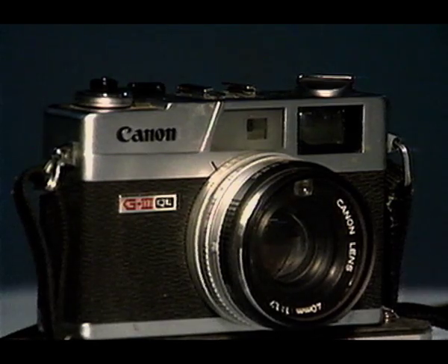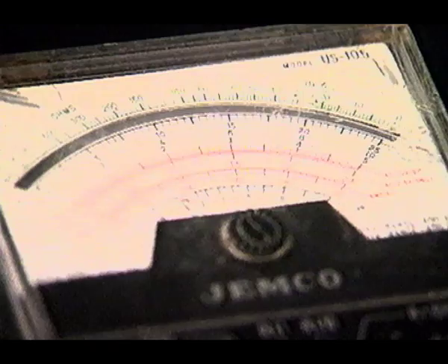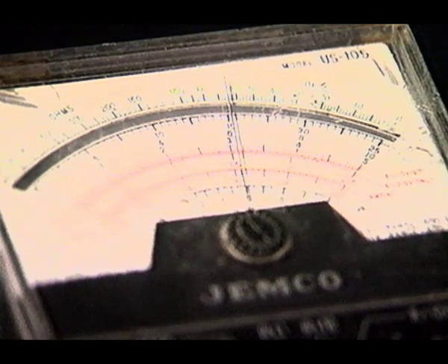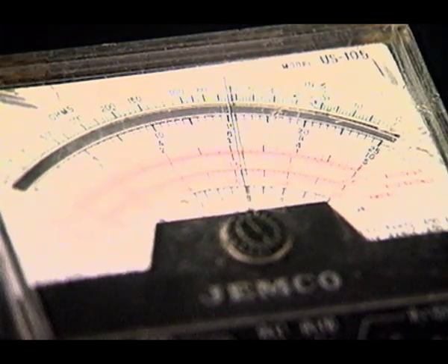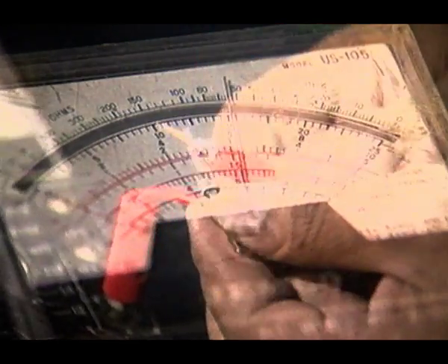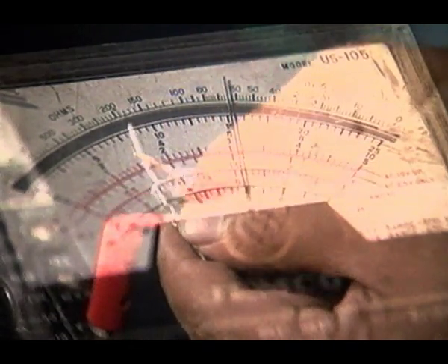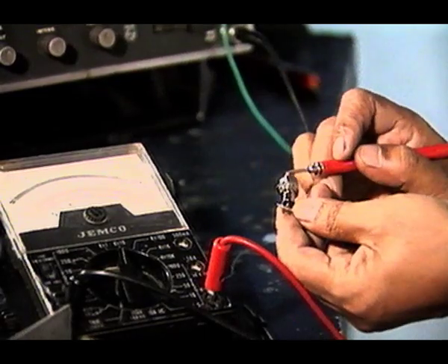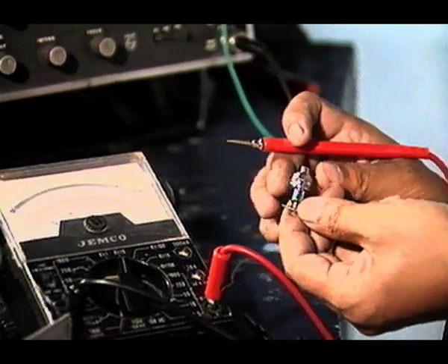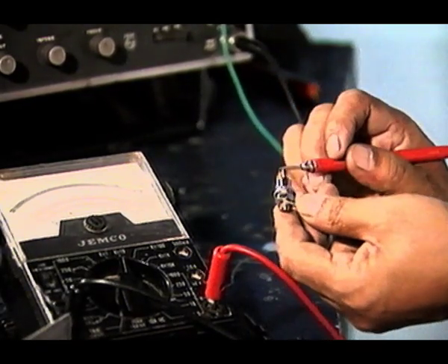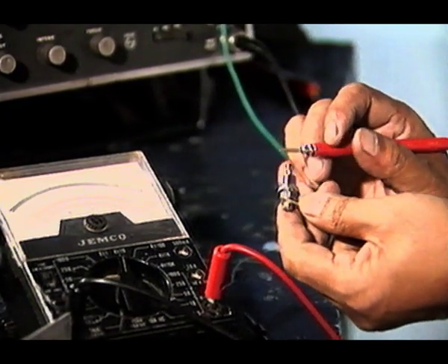How can one test whether a diode is okay or not? By using a multimeter or resistance meter. A burnt diode will show low resistance, no matter which way you measure its resistance, while a good diode will show very high resistance when it is connected in reverse bias.